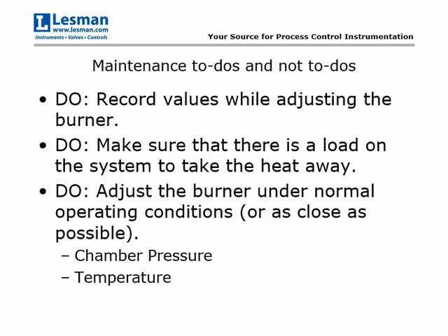Fortunately, I was working with a service technician that was keeping an eye on the system. We were able to put that fire out quickly, but it just shows the risk of setting this burner up by yourself and also without taking that heat away. So I want to make sure I emphasize that. You do want to try to adjust the burner under normal operating conditions.